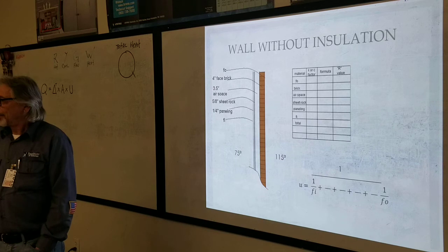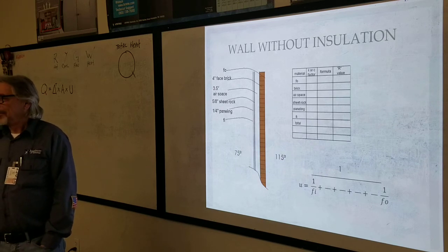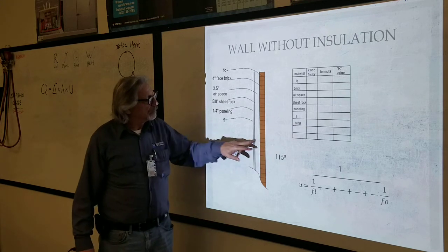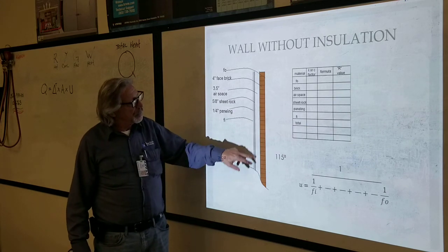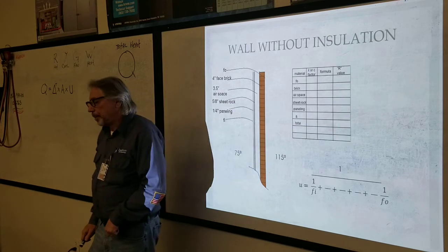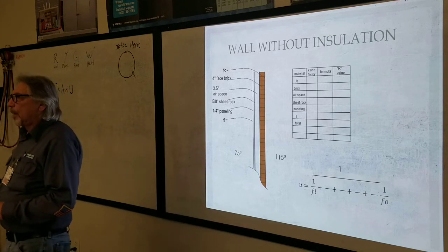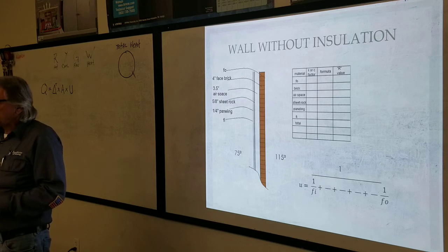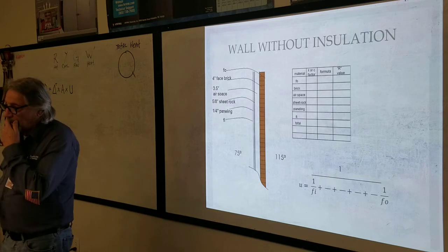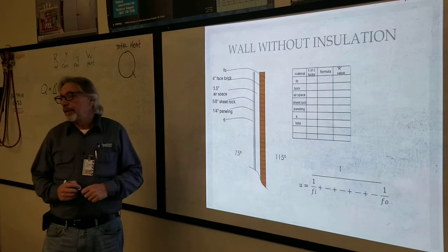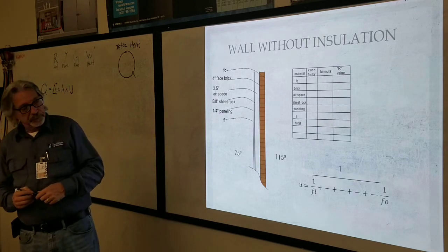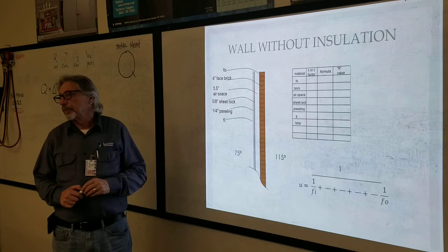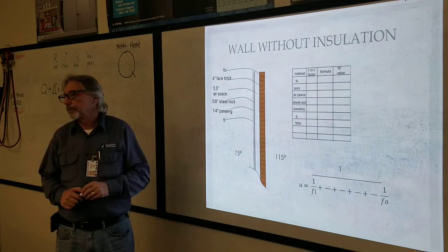Air film coefficients. Heat flows from the outside air to the outer wall surface and from the inner wall surface to the inside air by radiation, convection, conduction. The time rate of flow at these surfaces, combining the effects of all three methods of heat transfer, is known as air film coefficient or surface conductance, F, in BTU per hour per square foot per Fahrenheit degree difference between the surface and the surrounding air.